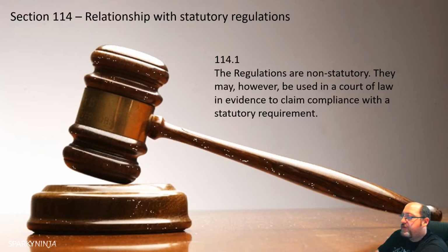The last bit of this, Chapter 11, Section 115, premises subject to licensing. This is obviously for installation premises over which a licensing or other authority exercises a statutory control. The requirements of that authority shall be ascertained and complied with in the design and execution of the installation. I've experienced this in a number of ways.